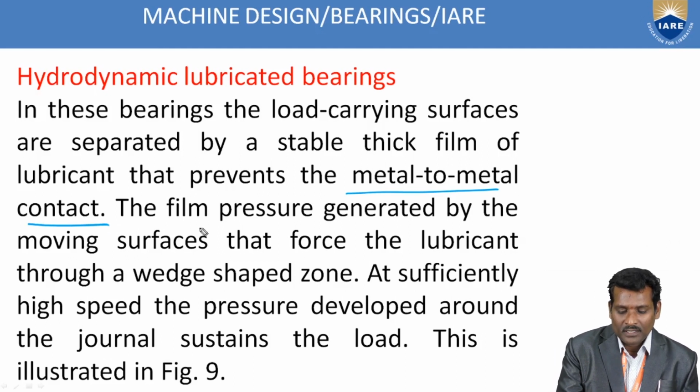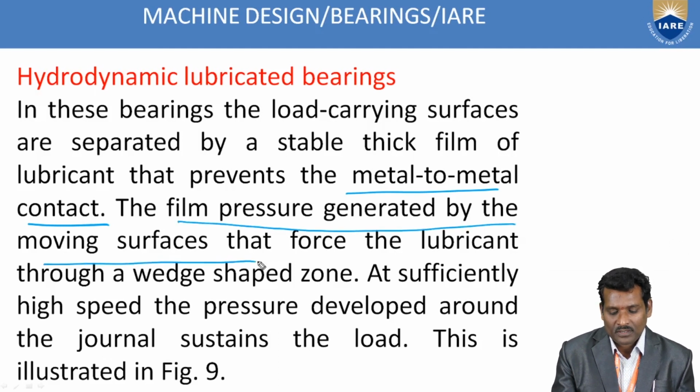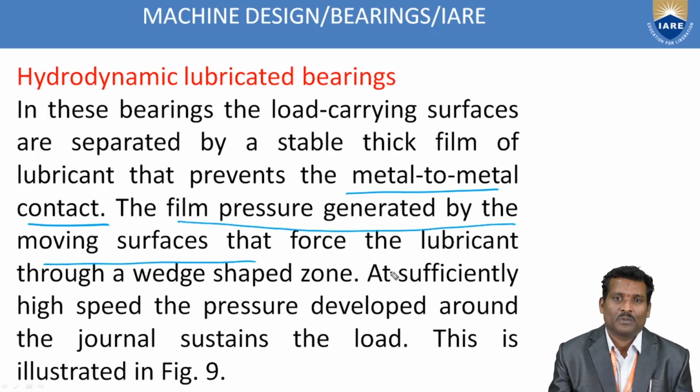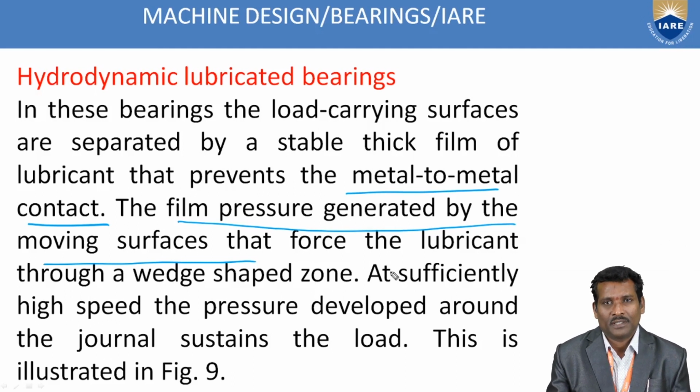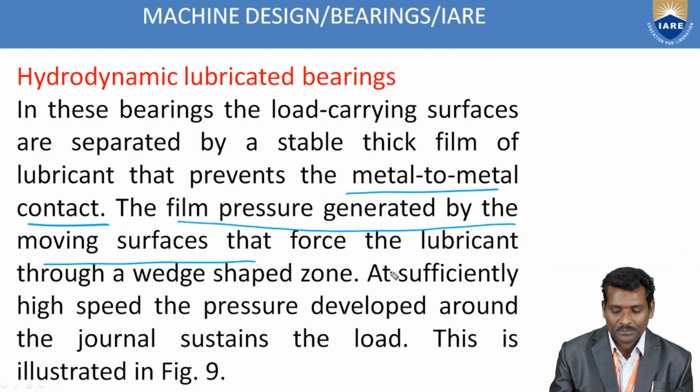The film pressure is generated by the moving surfaces, which force the lubricant through a wedge-shaped zone. So it means sufficient pressure is built up inside the bearing only. No external agency is needed to build up the pressure. That is the main concept of hydrodynamic lubrication bearings.